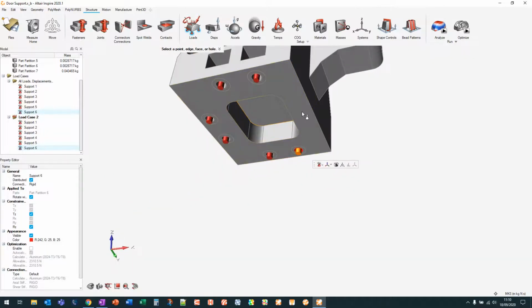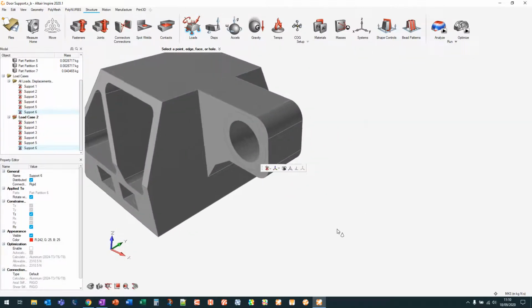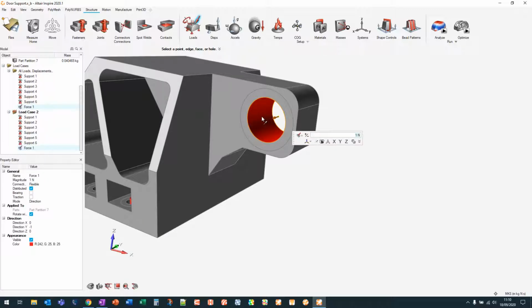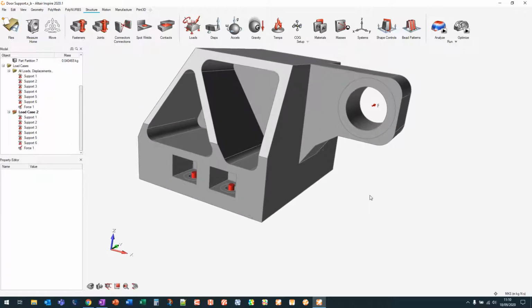Another thing that we now need to do is to apply a force. So we'll change this to force. And let's select the center of this point here. So we'll go for a value of positive y. We can either change the direction by pressing y, so you can see this arrow switching, and we can use the plus minus tool here as well. So let's say 1000 newtons, for example. So we'll right click and swipe to select that. So that's basically one load case now done.